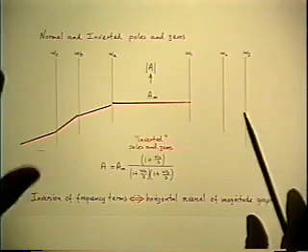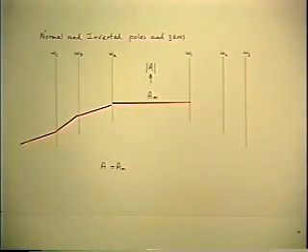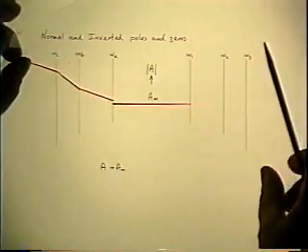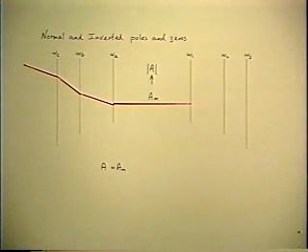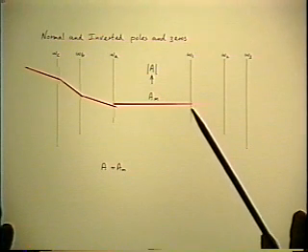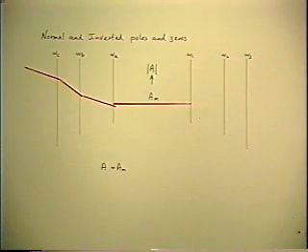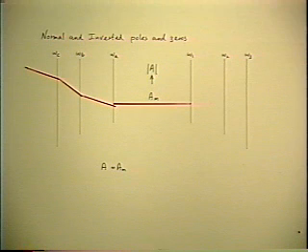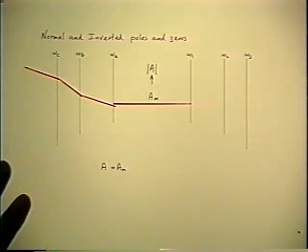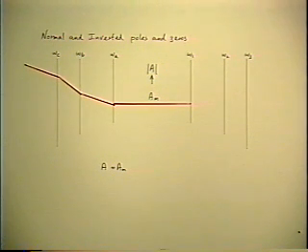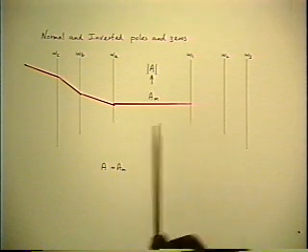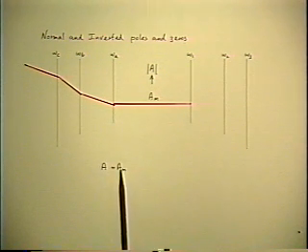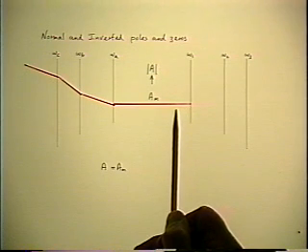Now, to give you a little practice of that, I'll take that away and I'll turn that one upside down, and you see that result is missing from the notes. That's because you get to write it in. So remember, the principle is write the flat gain first, A equals AM, because you're going to choose that as the reference gain.